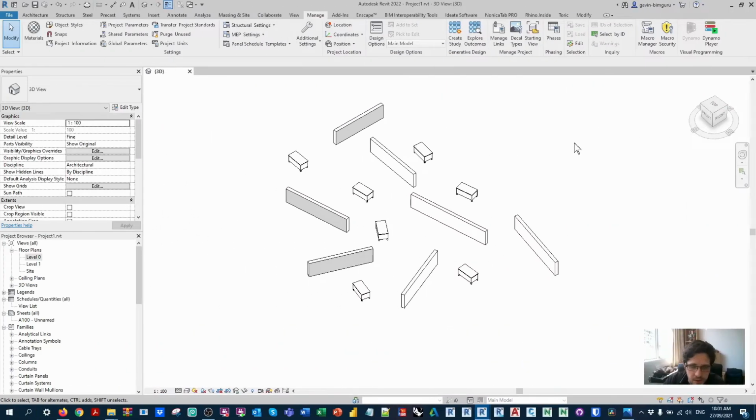So in this particular model, I've created a set of walls and desks, so walls and furniture essentially. In Dynamo, walls are typically represented as a line when we look at something like their location: 2 points that determine a line, a start point and an end point. A desk instead is represented by a point or its family origin.